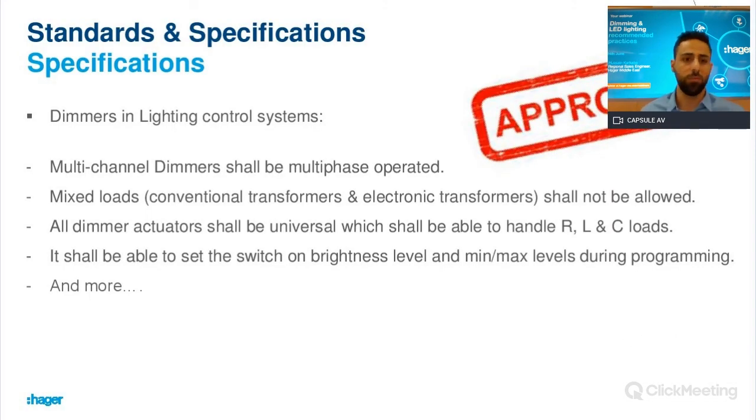Specification. I will go through a few. Multi-channel, multi-phase. Always keep it multi-phase. Sometimes we buy a dimmer that is low cost and monophase. You cannot install different phases, so you are stuck in your project.